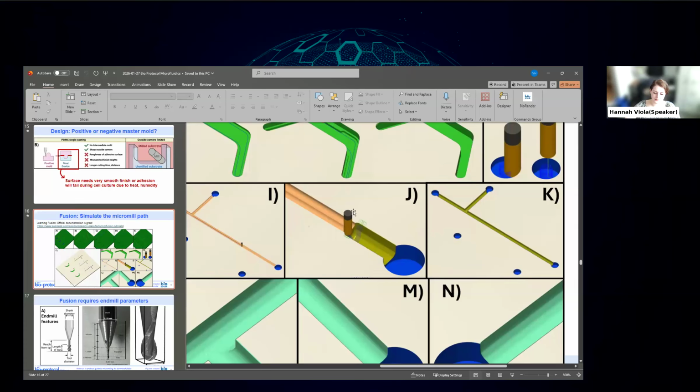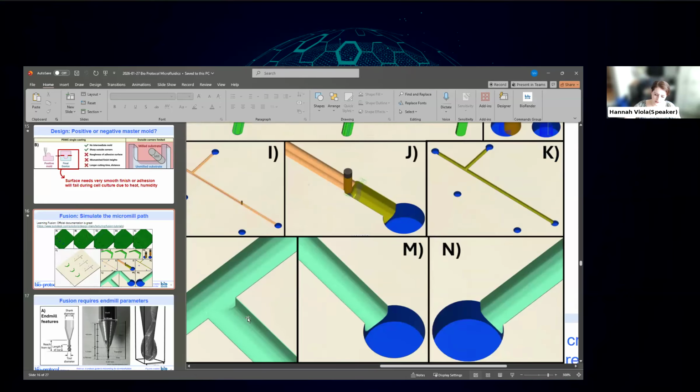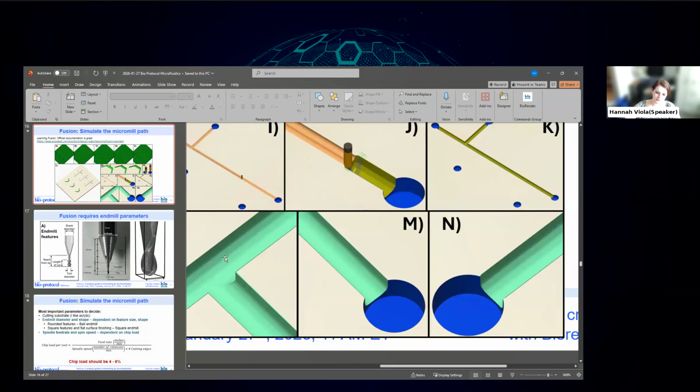It's still 0.1 microns for our machine. So the channel that I made was much larger than that, and most microfluidic channels are going to be on the micron scale. So the resolution will be good enough that you're not getting these ridges. There was a very slight, I think the surface finish in the simulation is very faithful to what my part ended up actually looking like. So you can tell that it was milled, but it's not so disruptive that it was going to affect my part, or that it was no longer optically clear and everything. And that's good enough for me.